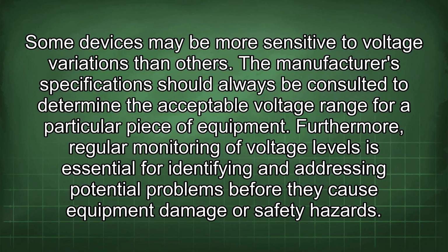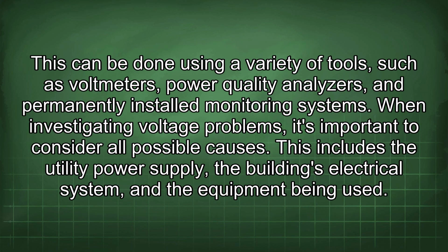Some devices may be more sensitive to voltage variations than others. The manufacturer's specification should always be consulted to determine the acceptable voltage range for a particular piece of equipment. Furthermore, regular monitoring of voltage levels is essential for identifying and addressing potential problems before they cause equipment damage or safety hazards. This can be done using a variety of tools, such as voltmeters, power quality analyzers, and permanently installed monitoring systems.